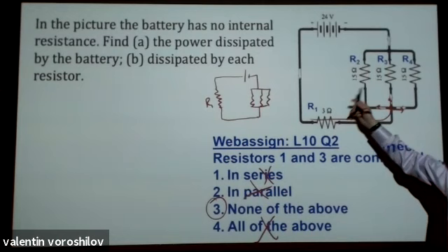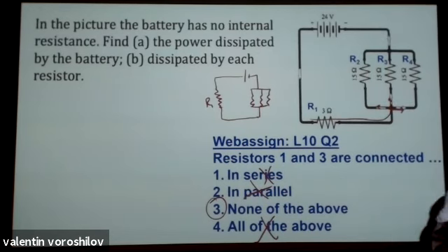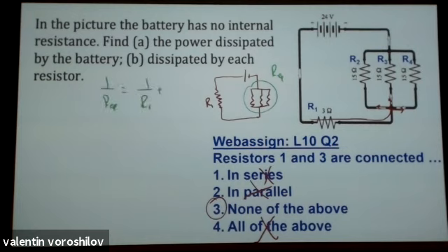And we can see these three are in parallel. And because they are in parallel, we could replace these with only one resistor, R equivalent. And for a parallel, don't make a mistake, okay, 1 over R equivalent should be equal to 1 over R1 plus 1 over R2 plus 1 over R3. Good thing they all are identical.